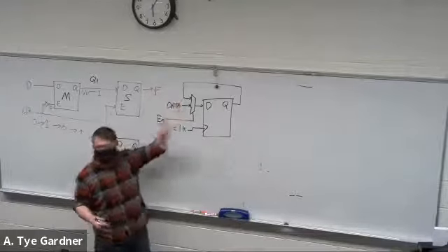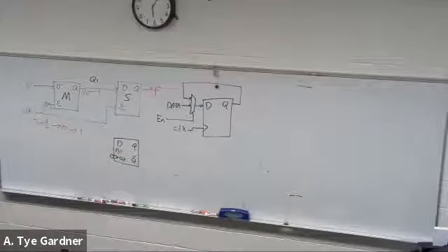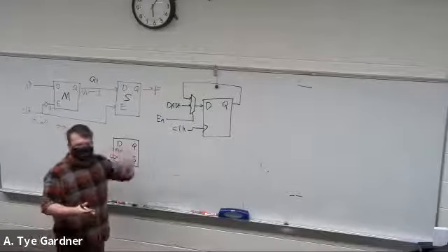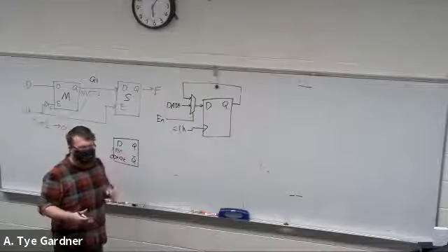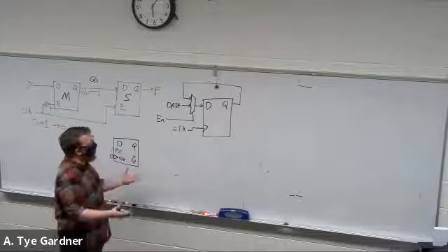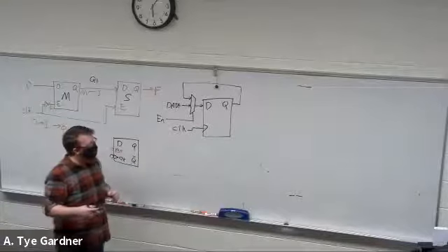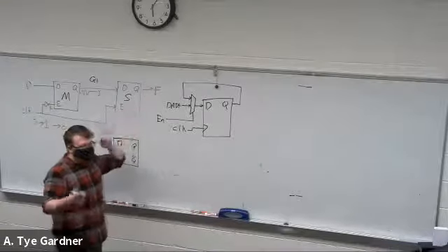So this is a good way of doing that, so that we're not gating this clock. We don't have to do anything weird with the clock. But we still get to choose whether to hold the same data or move on to the next. And there's no opportunity for this enable to really mess anything up. It can go up and down all at once, more or less.